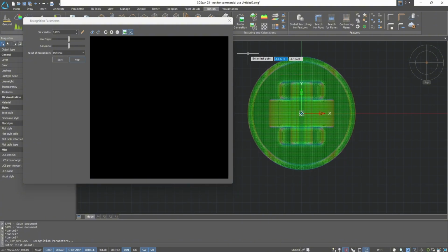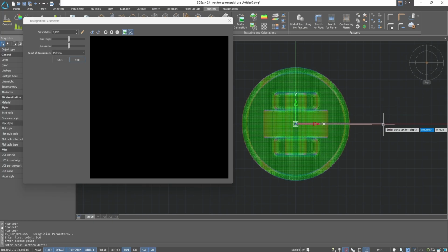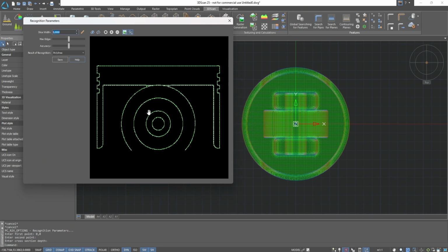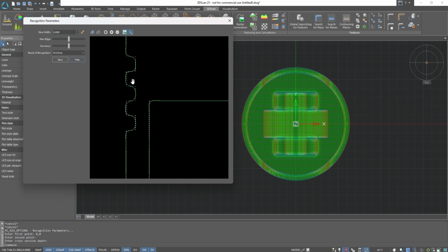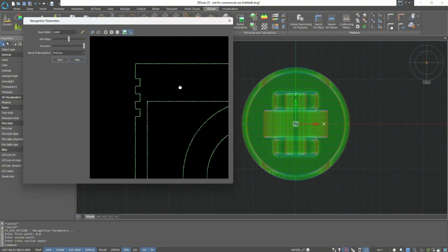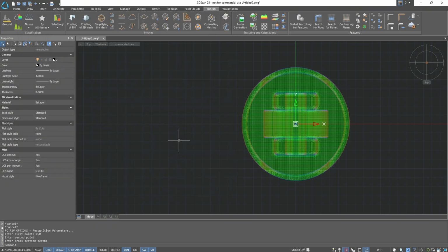Let's set the position of the section at the origin and specify a width of about 5 millimeters. Next, moving the slider's max edge and accuracy, we will select the optimal parameters, since later these lines will be the fundamental lines when building the model. Save the parameters and go to the next step.